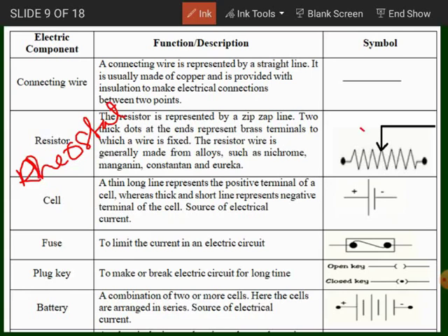And this is that rheostat. A rheostat will have three terminals like this. This one will be fixed. At the time of practical classes, if you are going to connect this rheostat, then one will connect here. Suppose one line is coming from the negative side of the battery and is connected here, then the other end should be left free, and the positive terminal should be connected onto this terminal. Got it? So when you slide this arrow above this resistance wire, depending upon how many turns are there in the circuit, your resistance in the circuit can be changed.